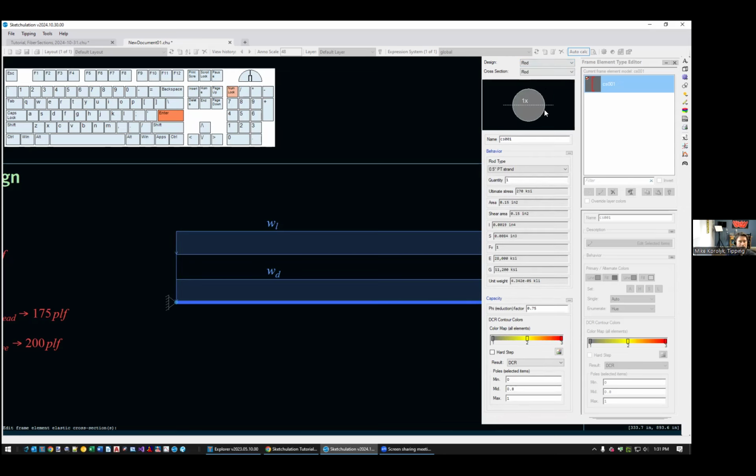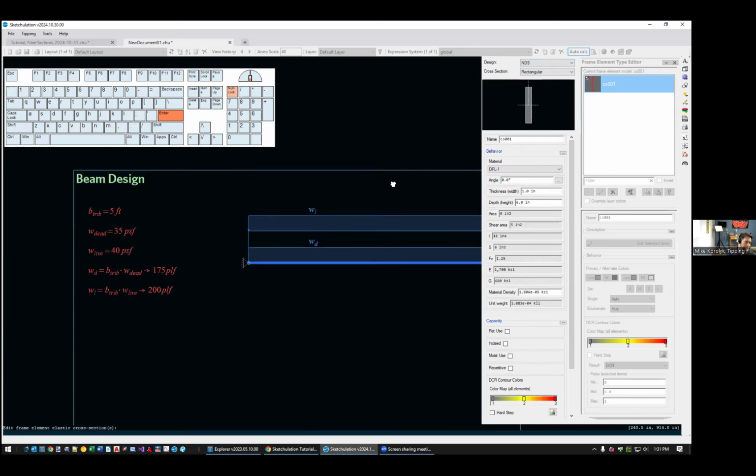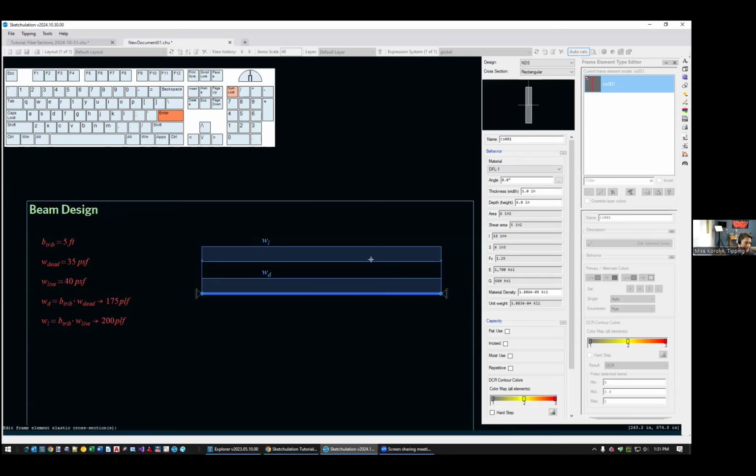And we have rods. So, if you had post tensioning or something like that, this is where you can choose different thin rod types. But we want an NDS shape. So I have no idea what size. Well, I could probably guess. I'm going to guess that this beam is going to work as maybe a 4x10, but you have glulams to work with. And you also have PSLs, other manufactured lumber, but I'm going to guess a 4x10 to start with here. I'm going to choose my material, Doug fir, select structural number 1.